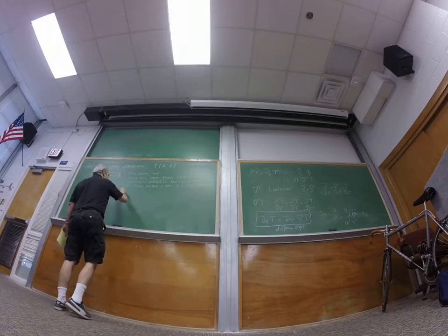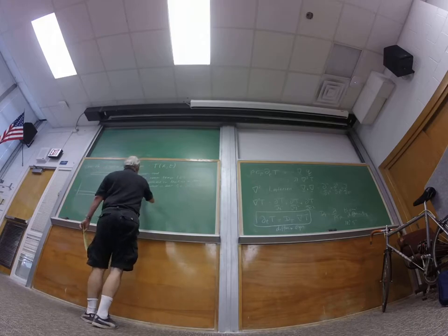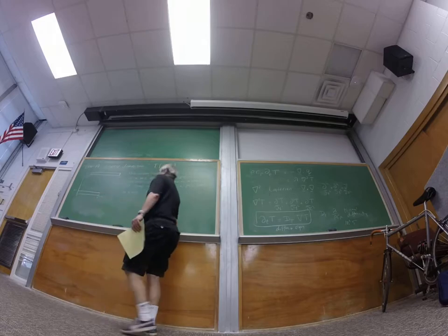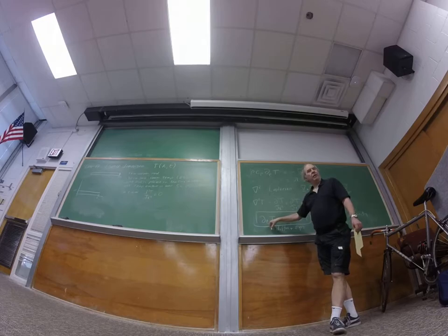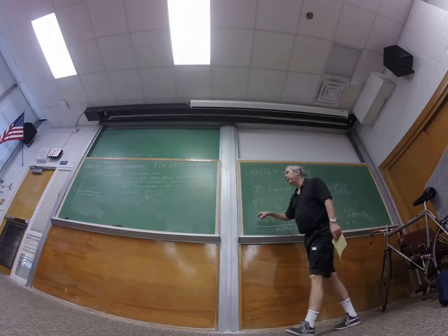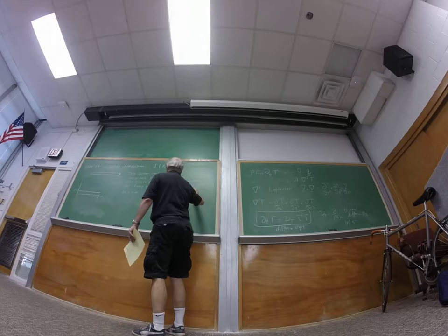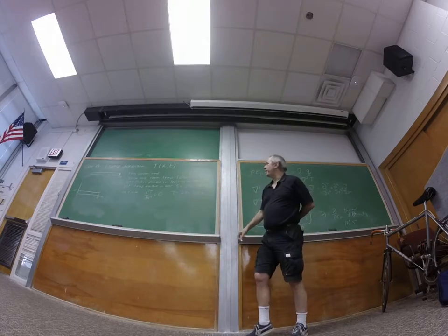So as time goes to infinity, then our temperature will be the solution of the equation, this guy, which you've definitely seen in elementary transport. Because if we wait long enough, we come to steady state, it means that the temperature isn't changing in time. So this guy would be 0. And then in that case, the solution of that is just T is 25 plus I think 2.5x, right? So that will be the solution at very long times.